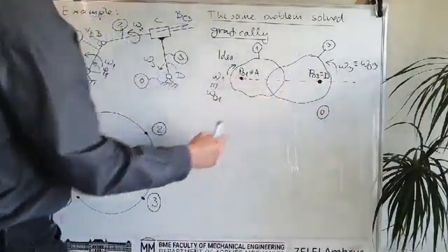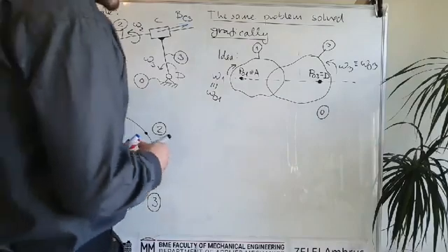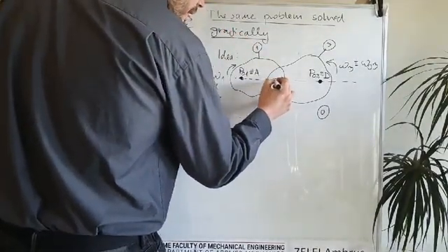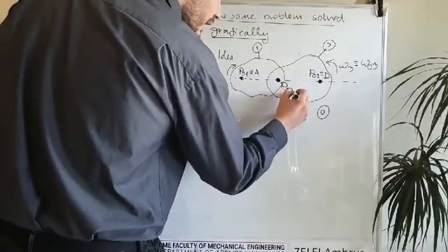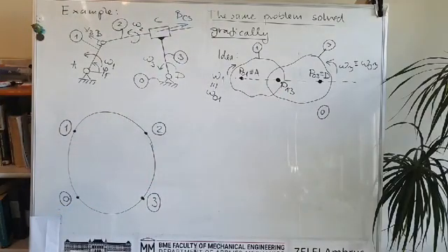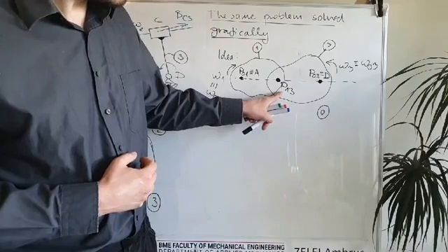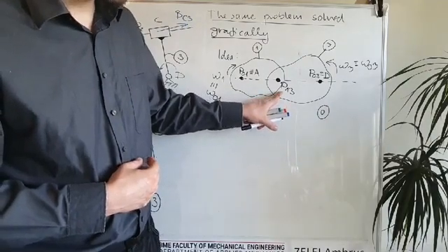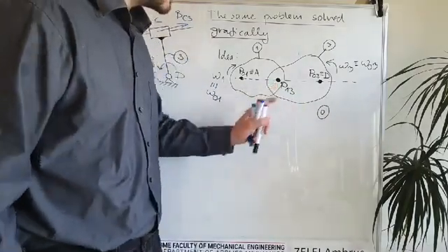This is the point where it is fixed to the ground, and we can assume, based on the Aronhold-Kennedy theorem, that there will be somewhere an instantaneous relative center of velocity called P13, and its meaning is that, knowing the definition of instantaneous relative center of velocity, the velocity of the 2 rigid bodies 1 and 3 are equal to each other here at this point.